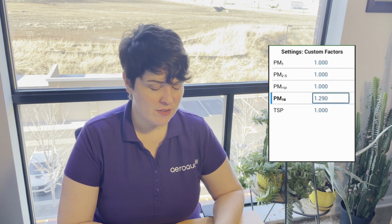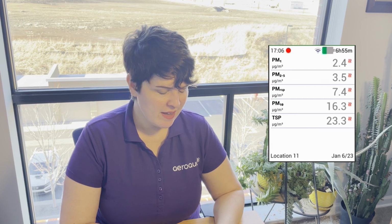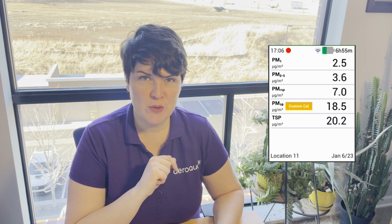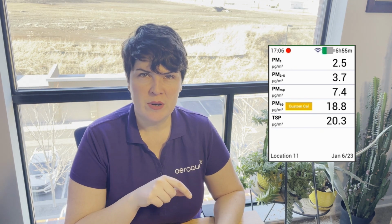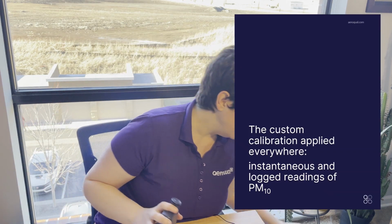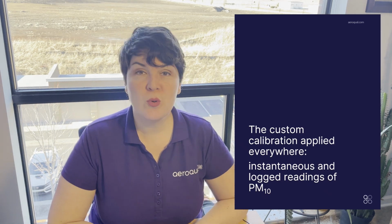Let's exit the settings menu by pressing and holding the left arrow key. And you will see that a custom calibration factor label has appeared next to the readings for PM10. Note that the custom calibration stays with the PM sensor head. So if you were to remove the sensor head and attach it to a different Ranger base, the custom calibration factor would stay with it.